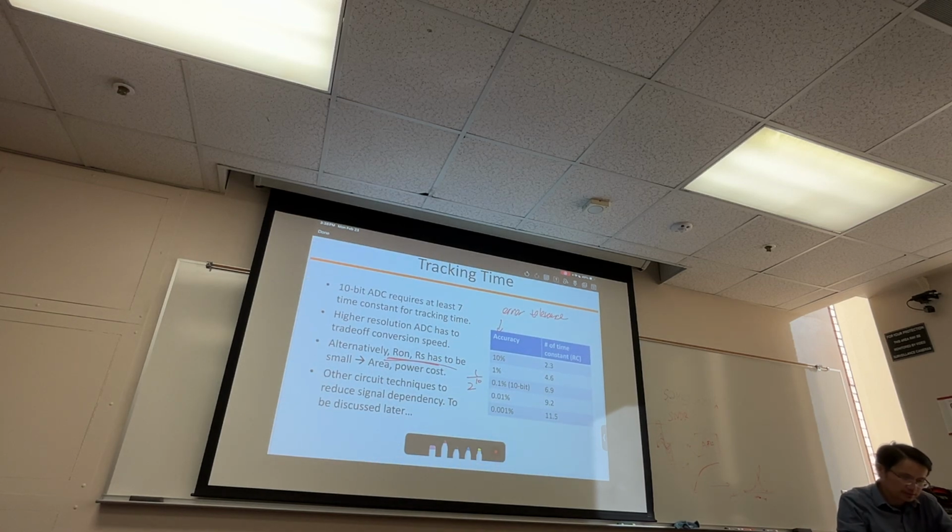And then the same as the RS, right? So this is one question I asked you. If you amplify and you want a low output impedance, you also generally need to burn more area and power. Okay, you most likely need to size up some of the things.